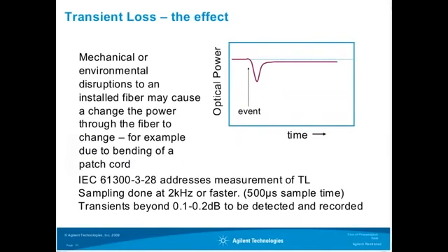I think we've pretty much gone through essentially what can happen there. For instance, with a connector, you could have the case of pistoning when the temperature changes, having the two ferrules of a connector pull back or away from each other a little bit and create a gap in the fiber connection, and then produce a drop in power. And then typically if fibers are bent, that's going to cause some increase in the attenuation of the fiber.